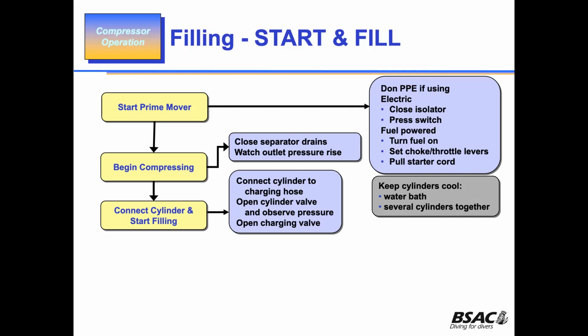The cylinders do tend to get warm, but they don't tend to get that warm, right? Again, it all depends how you do it. It's really so you don't have to keep doing another top-up fill after you've finished, because when the cylinders start to cool down, the pressure will drop, part of the gas laws.